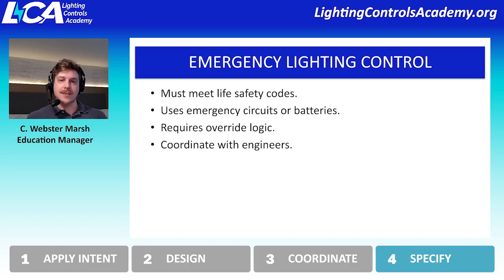When we are finalizing the emergency lighting controls design, however, we do need to make sure that this is coordinated with engineers so that they can confirm that, yes, this is going to meet the requirements. Because if, for instance, you're a lighting controls designer and you're not an engineer, regardless of emergency lighting control, you do need somebody to stamp your drawings in a commercial environment. So having an engineer involved is critical to the success of the project. But if you're doing emergency lighting control design, especially, you will need to coordinate with the engineers to make sure that it meets their needs for emergency egress lighting.